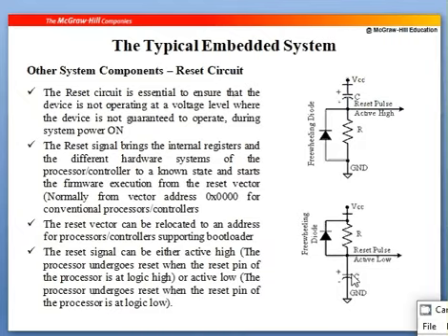Ensure that the capacitor discharges quickly in this case, so you get a low pulse for a while. Then all of a sudden, if you get a proper voltage, you get high voltage. So active high will continue. When you have an active low state for a while, at that time this connection has to be given to the microcontroller to reset.